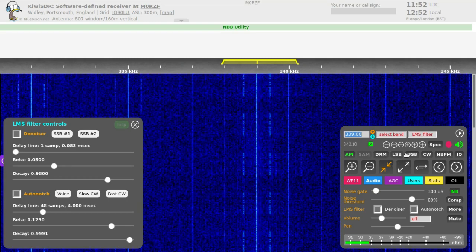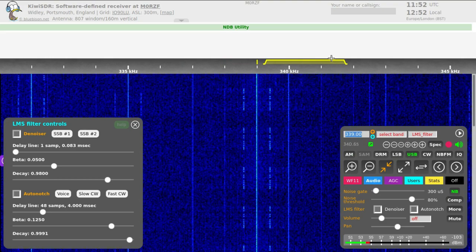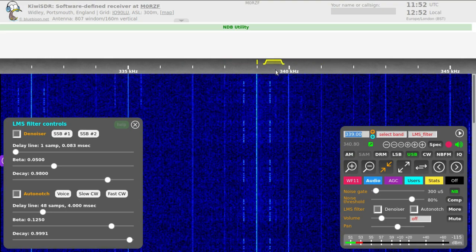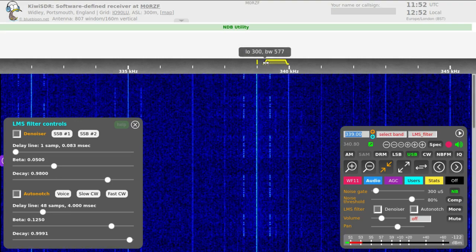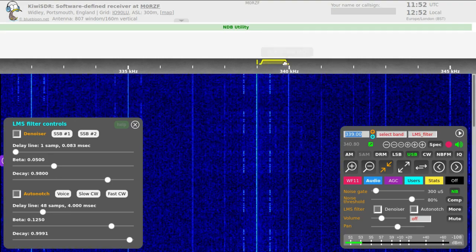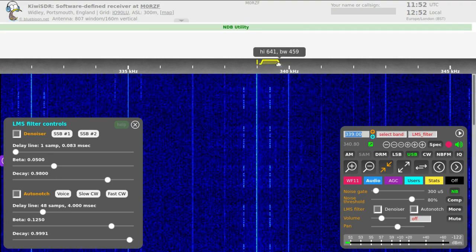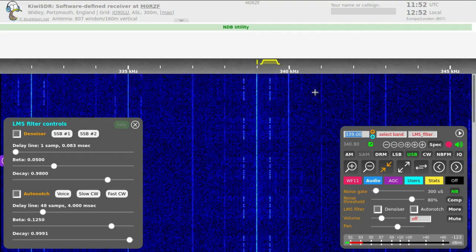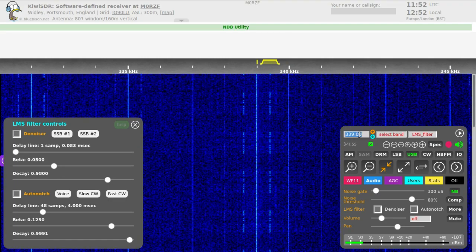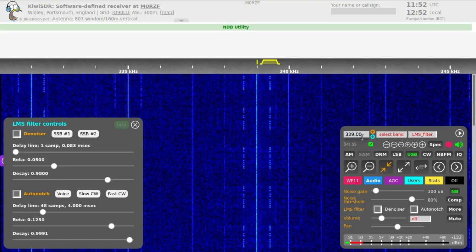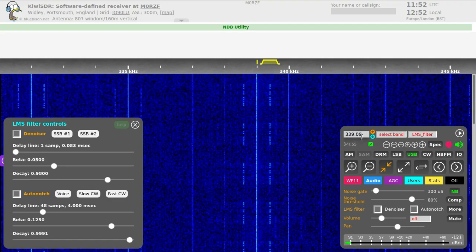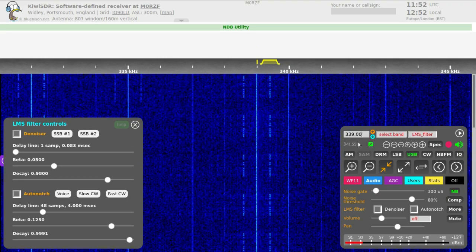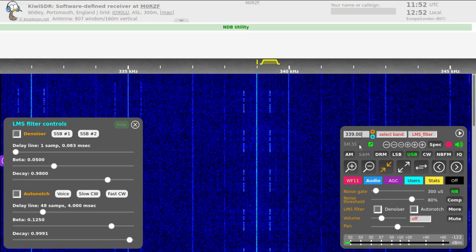There is another way, which is to go to single sideband, pull in the filter passbands, and only allow the Morse identification through. If you really want to pull weak non-directional beacons out of the noise, do this. It also works on VHF if you're listening to localizer or VOR transmitters.